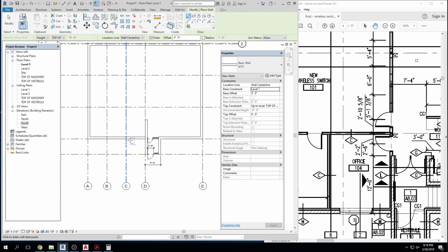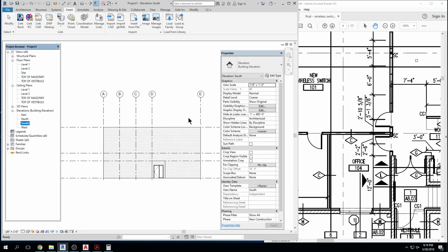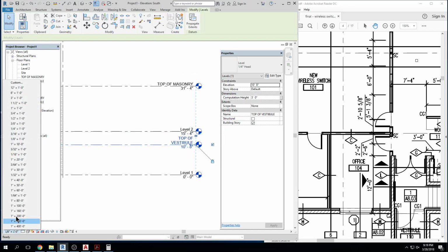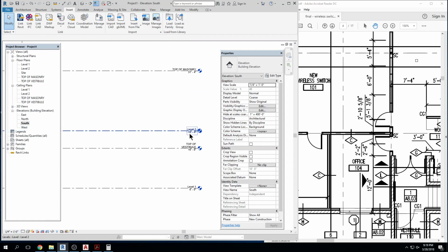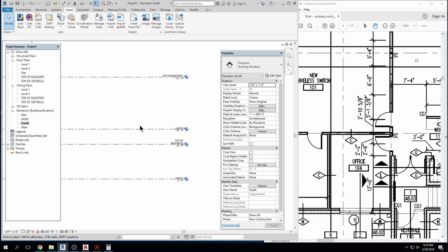Okay. So my walls are going to be defined from level 1 up to, well, if I take them to level 2, when I place my floor, the walls are going to bleed through my floor, right? So before I draw these walls, I actually have to create another level. I'm going to go back to my elevation views, and if this is level 2, this is the same thing as with our house that we drew, where we had the main level and then we had bottom of structure, right? So we need to create a bottom of structure level here.